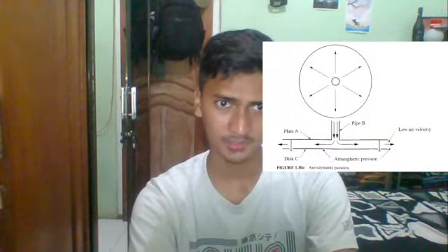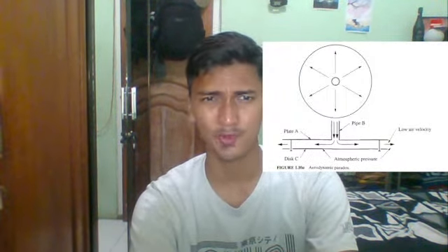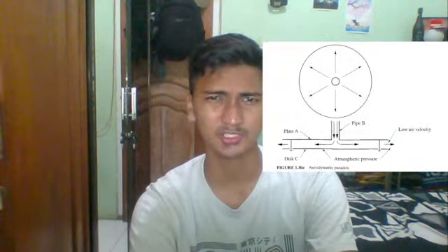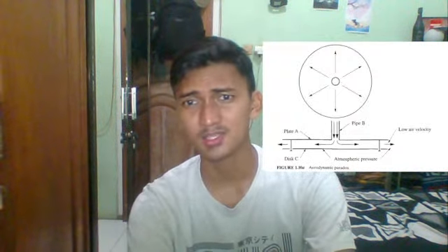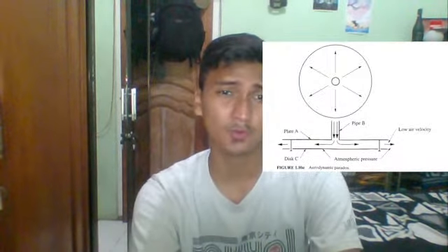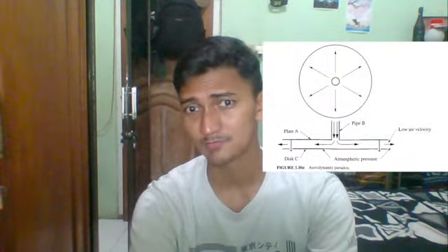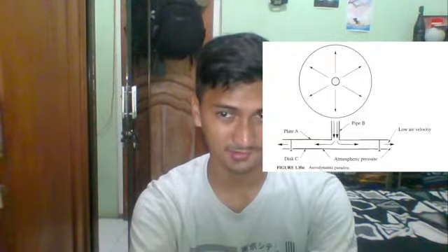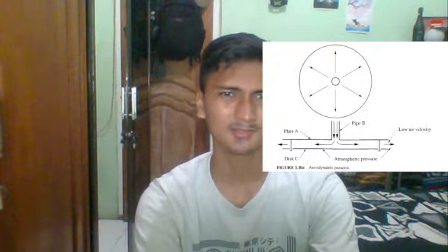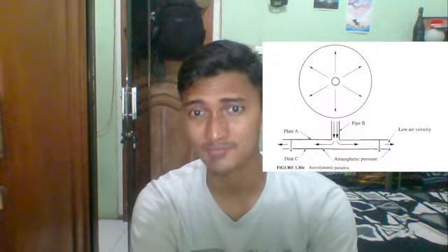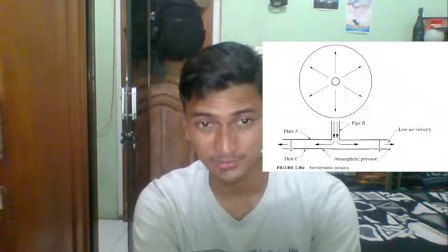For the inside, however, where the cross-sectional area is much smaller, the velocity of the air flowing outward is larger, and per Bernoulli, the static pressure therefore is lower than the atmospheric pressure that pushes against the underside of the lower disc.